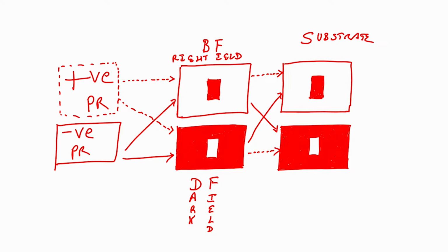You see, this area is exposed, this transparent thing is exposed. So, we have here this pattern. In this case negative photoresist, I am talking about negative photoresist. In this case bright field mask, the area that is exposed is stronger and the area that is not exposed will be weaker, you can see here, right.